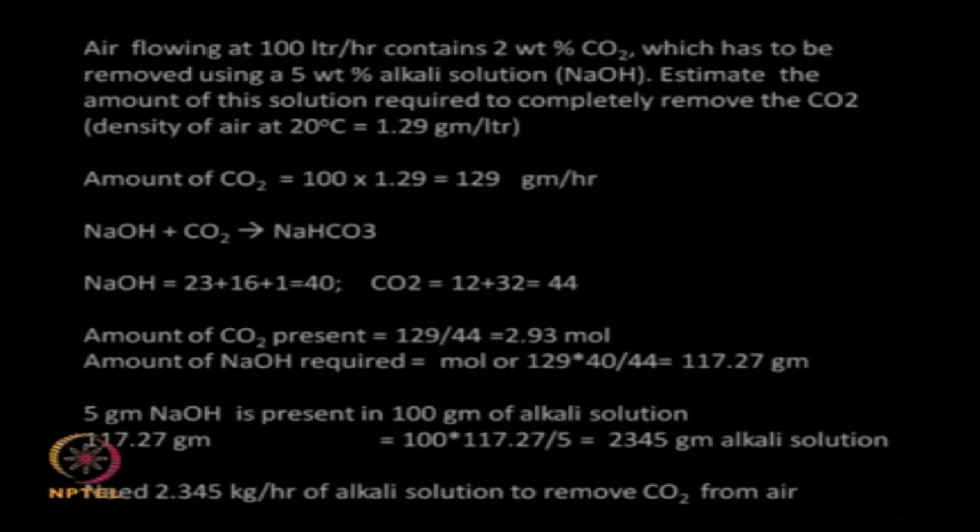So what you have is air coming out at 100 liter per hour, and it contains 2-8% of carbon dioxide, and this has to be removed using an alkali solution. That means sodium hydroxide dissolved in water, that is aqueous alkali solution. Now it contains 5-8% of sodium hydroxide in water. Now the goal is to estimate the amount of solution required to completely remove the CO2 that is coming out.